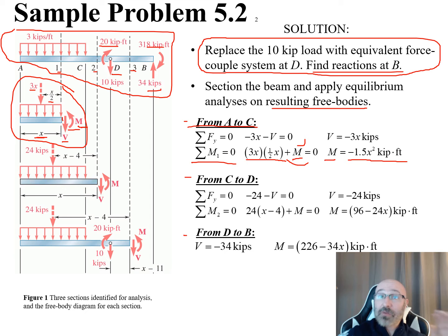And again, this is all dependent upon x. So this could be for any value of x. So this is very useful if we want to step this along the way and figure out what our shear and our moments are at any distance between A and C, any distance from A in that range right there, we can do this here.